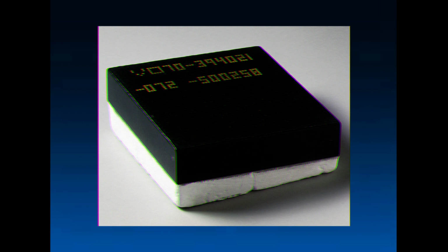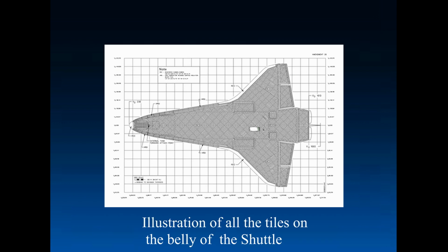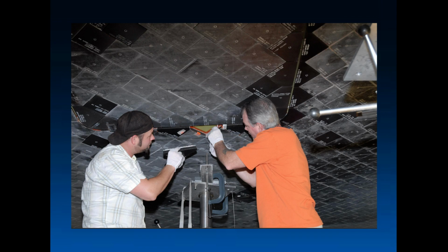When the Space Shuttle re-enters the atmosphere, it faces downwards to increase drag to slow down. But when they re-enter the atmosphere, the air predictably gets really hot. To counter this, the Space Shuttle uses LI-900 silica thermal-resistant tiles. However, the shuttle needed 21,000 of these tiles, and each of them had to be either checked or replaced.